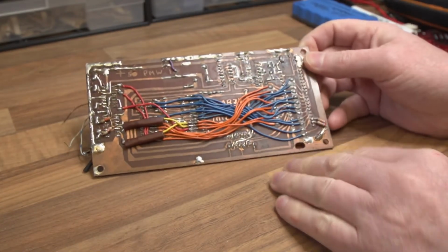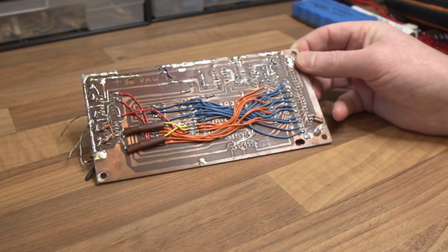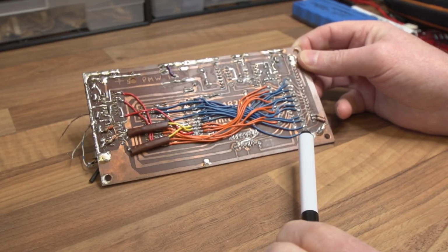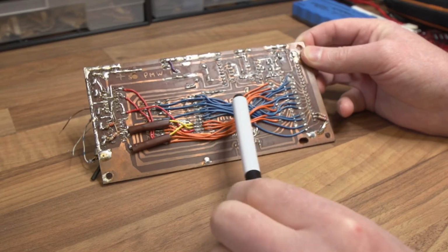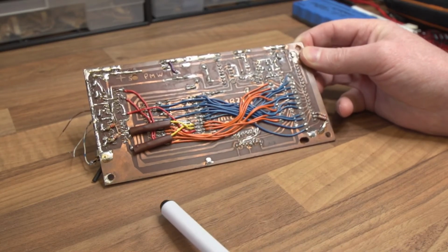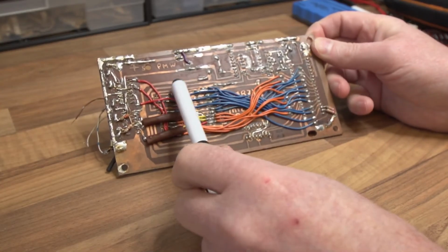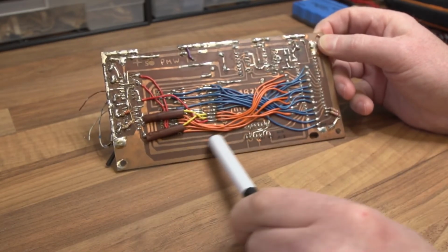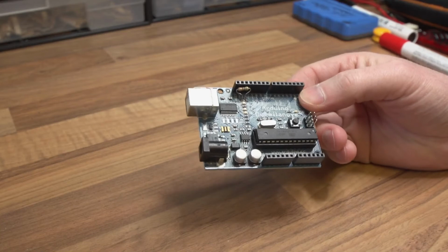And I can show you the back just for laughs. This is what we did back in the day. That's a handmade PCB that I did with a marker pen. If you watch one of our first videos on making PCBs and using prototype boards and that sort of thing, I explain how you make basically a PCB like this. But as you can see, we've got a lot of wire on here as well, because this was in the day before I could do double-sided boards. This is a single-sided board. You know, there's no tracks on the top. There's only tracks on the bottom. So in order to get wires and tracks to cross each other, I had to use wire links. So you've got a combination of copper tracks, the actual PCB itself, and then you've got the actual wires which cross point across that.